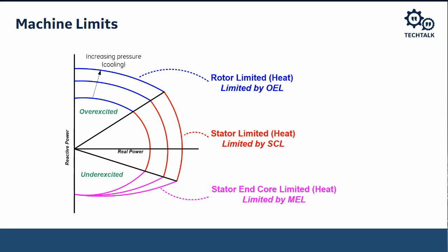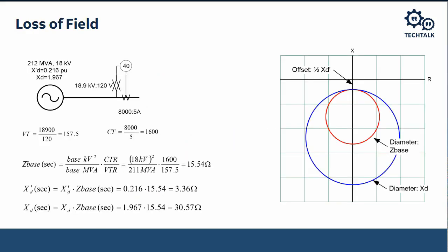And so this is problematic for the loss of excitation element, because this particular device, a G30 UR relay, uses an offset distance element to detect loss of field or loss of the exciter. Basically, on a resistance-reactance diagram, if we're providing real power, we should be somewhere to the right of the origin along the resistive axis, and also somewhere above the origin on the reactive axis.